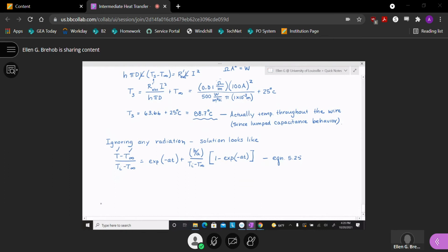So if I'm looking at this part of the equation, we know what this final temperature is. We know what the temperature of the bath is. We know the initial temperature, T infinity. And we've got a little problem there, but let's look at this for a minute longer. We said that it's a combination of things like rho, heat transfer coefficient, some surface areas. Okay, and here's our unknown time.